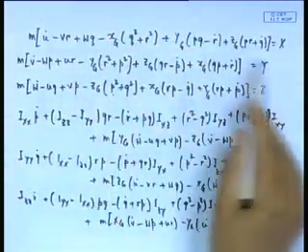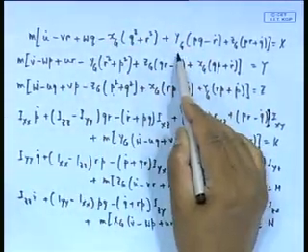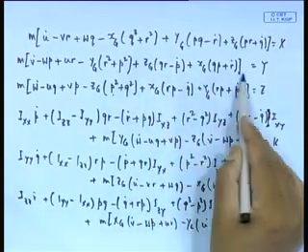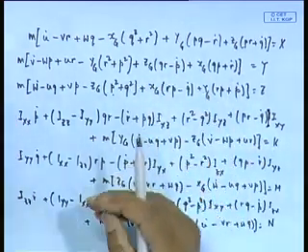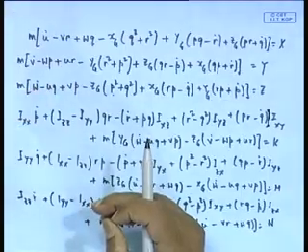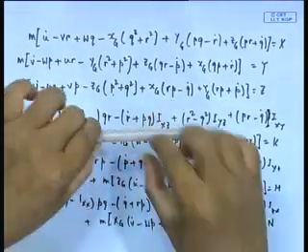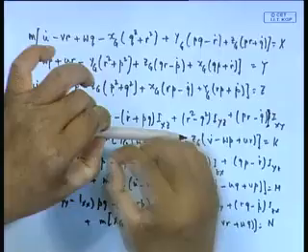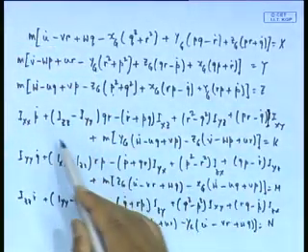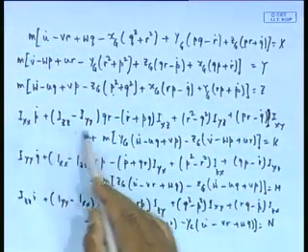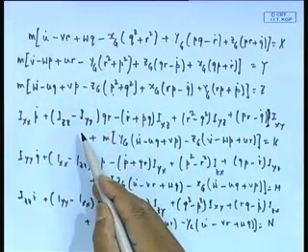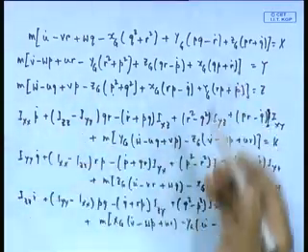So here this is okay. And the additional terms also come like that, y_G, p q r, etc. All these are coming because of the fact that there is a rotation at a different point from where you are taking the force. You are taking the force here, but rotating about this point. So as you rotate here, there is a component of force that comes. If you look at this rotational component, you have p dot. Now, these terms, I_zz, I_yy, q r, are again because of the fact that this will of course always come from the expression.